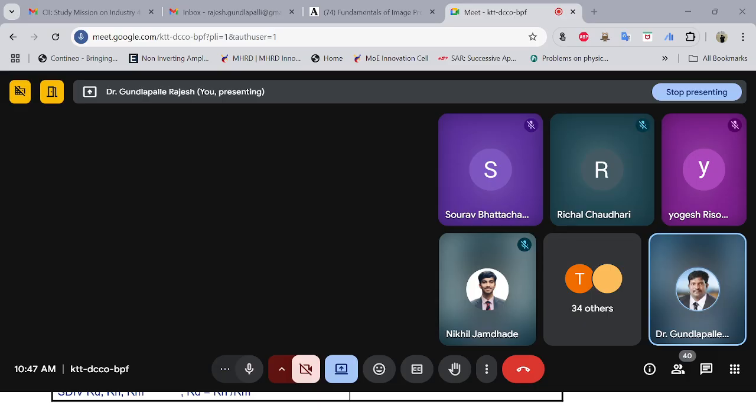The first one will be the destination. Let us take the add instruction for performing the addition operation. In the add instruction, you have the first operand as your destination all the time. Then you have the two sources which are referred. So in this instruction, the contents of Rm will be added to Rn and the result will be stored in Rd.